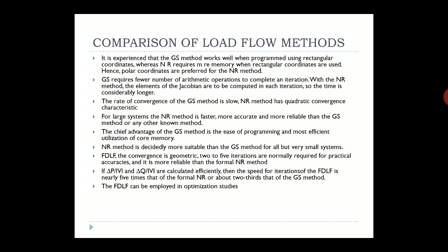Okay, so faster methods like FDLF are much more used. And there are further methods like the DC load flow, which is much faster. Now, is it accurate? Absolutely not. You cannot get the exact solution, but it is an approximation that tells us, okay, it is working fine, while I'm continuously monitoring the system state.